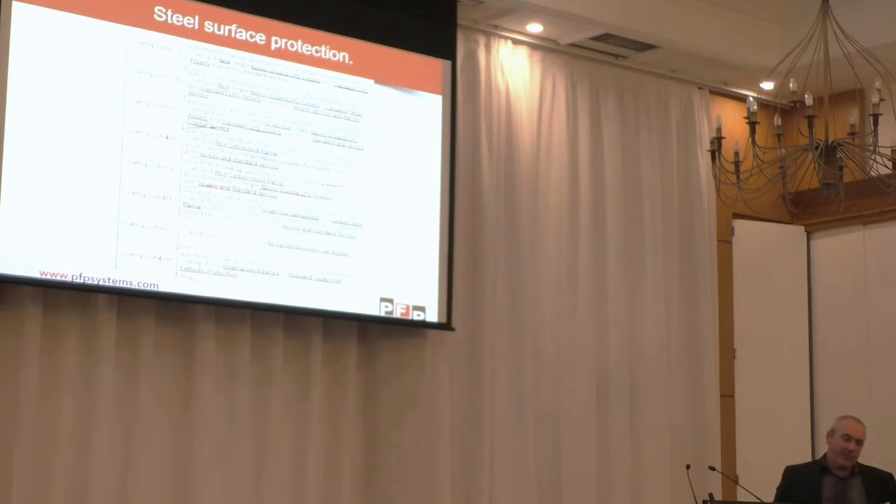So on the face of it, for the coating underneath the passive fireproofing, we could choose one of two, which would be D and E from the asset owner's specification, because that directly refers to the fire system. However, when it got down to where the vessel was and what the dangers were, they opted for coating system H, which is for buried tanks.